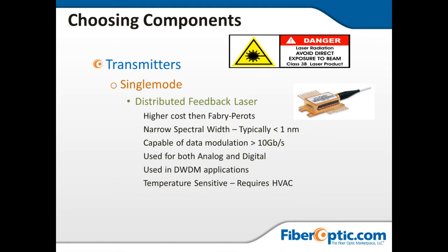Now, when you think about the 1 nanometer width, if you're doing any type of multiplexing, in this case we mentioned dense wave, that just means I can get signals at different wavelengths much, much closer together without stepping on the adjacent wavelength with other distribution issues.